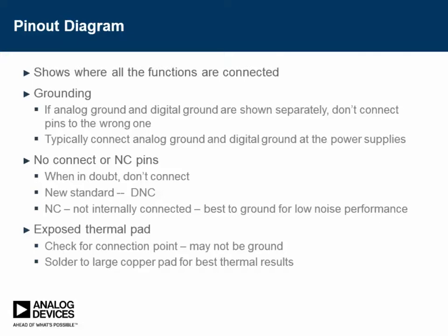You'll also find that there's an exposed thermal pad on many products that are used at high power, and make sure you see where that pad should be connected electrically. Most of them should be connected to ground. Some of them will be connected to a power supply, and you want to solder that to a large copper pad to get very good thermal results.